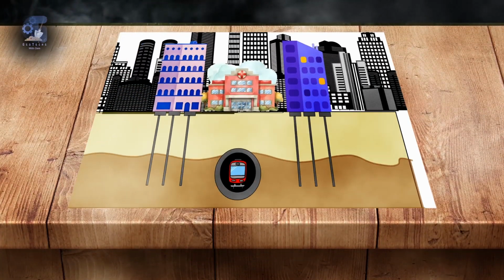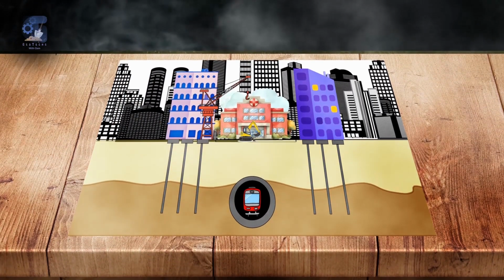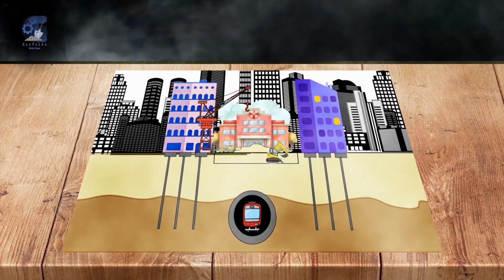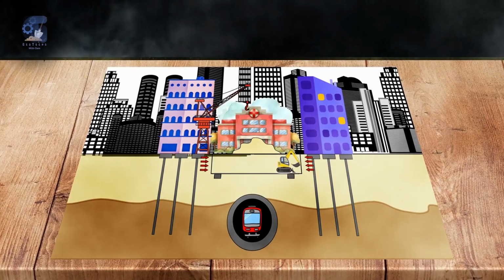Engineers have to acquire detailed knowledge of existing structures and their foundations, and also the information on tunnels within and immediately beyond the site boundaries, the presence of sensitive apparatus within adjacent buildings, and locations of hospitals or other buildings having special purposes that may have specific requirements. This is very important because when installing a new foundation, ground lateral movements should be kept at a minimum to avoid interfering with the structural integrity and service provisioning of the surrounding infrastructure.